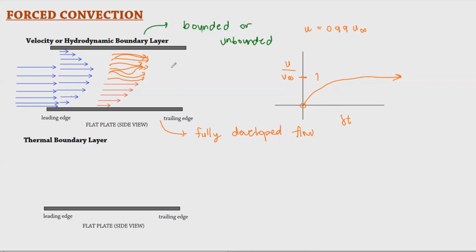And when we have turbulent flow, the layers of these streamlines will be messed up and disturbed. We call these the wakes or the vortices that are formed during this water transport, and it happens when the fluid has a very large velocity. So the inertial forces of this fluid overcome the viscous forces that are inherent in this particular fluid.